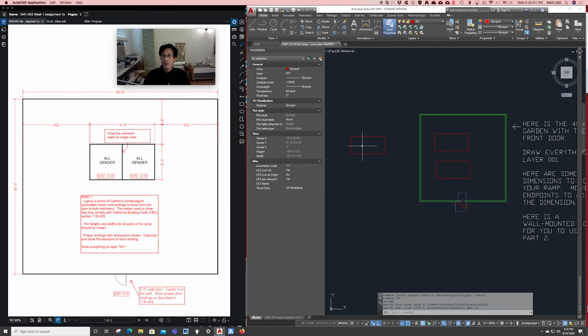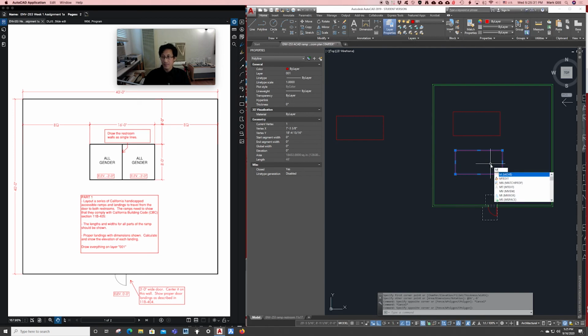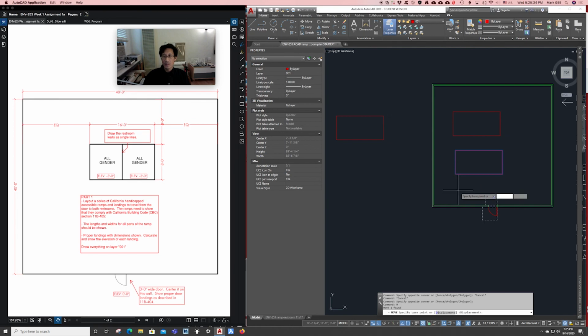Let's go ahead and keep it there. But let's do the move command and move this one out of the way, and we'll keep the line-based one and move that into place where we need it. So select this by clicking, move the mouse, blue box, left to right, have to encompass the whole thing, click, selected. Move command, M is the shortcut, space. Now, just like with the line command, where we do a direction and the distance, same thing.